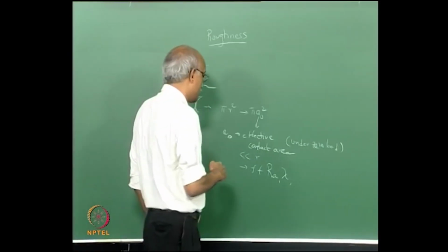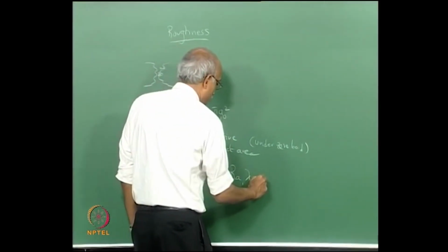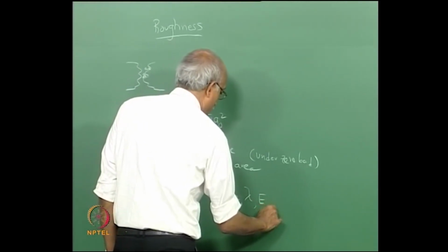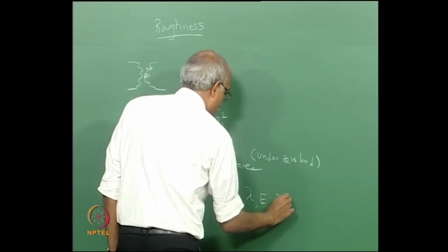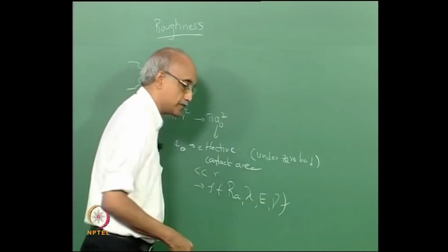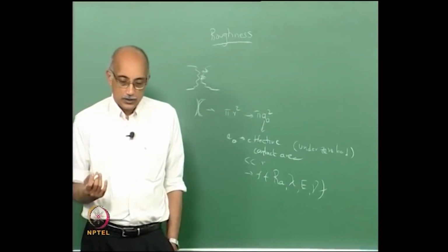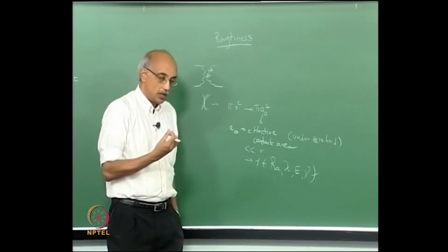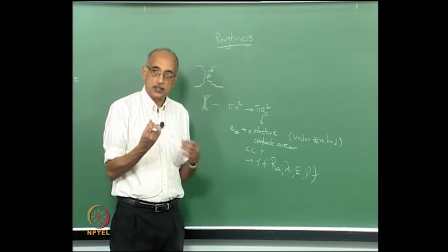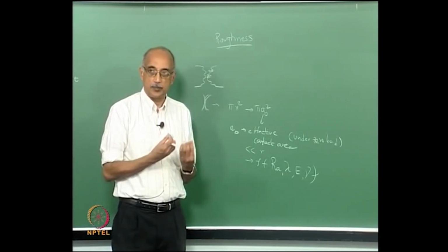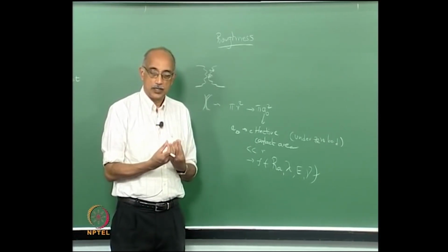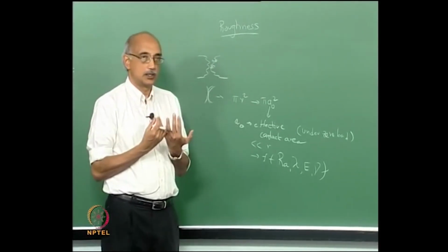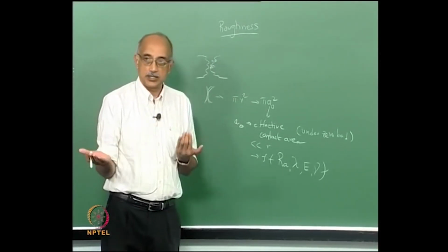It also depends on the properties of the particles, particularly the elastic modulus and the Poisson's ratio, because they have a significant bearing on whether contact between two adjacent particles occurs in an elastic manner or a plastic manner, because adhesion or cohesion is very different in the elastic limit versus a plastic limit.